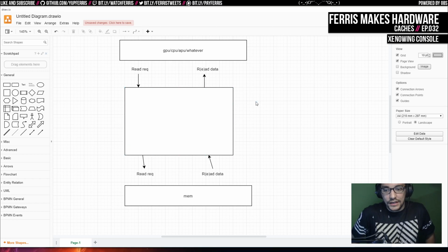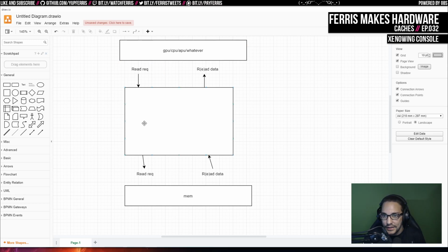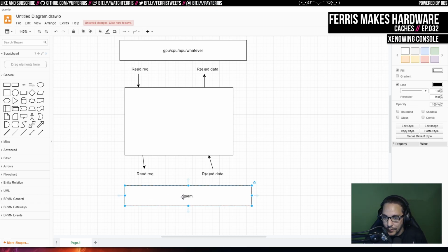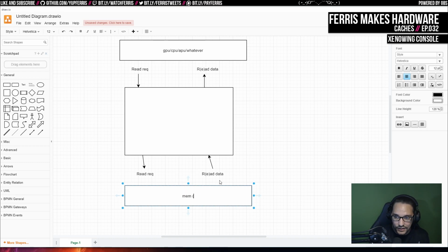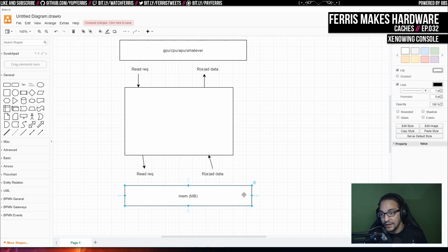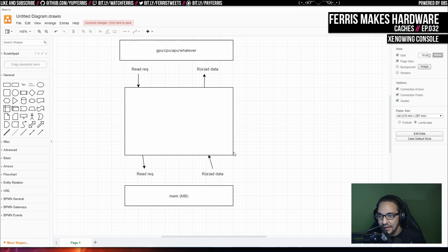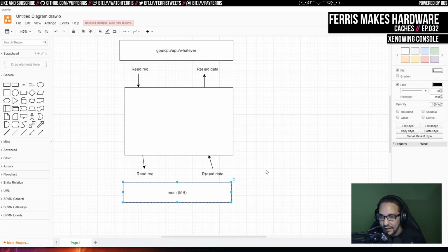And the best we can do with the memories that I'm using in this FPGA is that we get them on the cycle following when we issue the read request. So ideally, we want that consistent 1 cycle delay, but this memory will usually have like a 30 cycle delay. And that's a cost that we pay because we get a lot more capacity. This is like megabytes, where the cache, like internal memory on the chip, is in the kilobytes range. On modern SoCs, it's a lot more than that, but not on an FPGA, especially not a low-end one like I have.